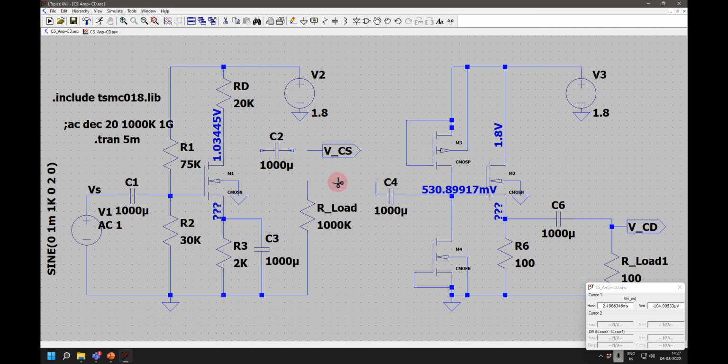Sir, this C4 capacitor is to lock the DC. Yeah, DC. Because see, this DC operating point and this DC operating point were different. So that is the reason I had used that. So now, like somebody suggested, we can do that also. It will be an efficient way of doing it. So now let's try and do that.